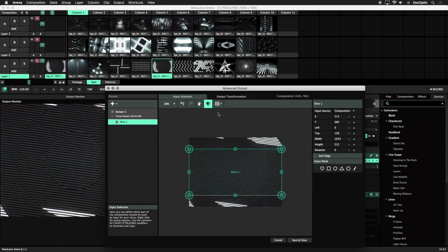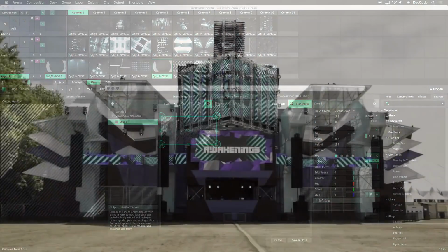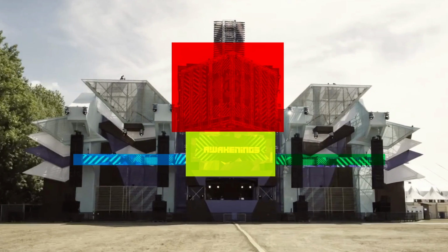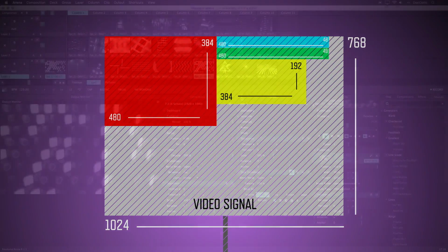Let's discuss the process for a more complex situation with the 4-screen LED wall. Imagine your stage looks like this. Unfortunately, the 4 screens are positioned like that on stage, but not in the LED processor. In the LED processor, the arrangement may be similar to this image. This minimizes the data sent along the cable connecting the LED screens. 4 screens like this are still controlled by a single LED processor. Only one signal from your computer's output needs to be sent out. The processor divides it over 4 screens.